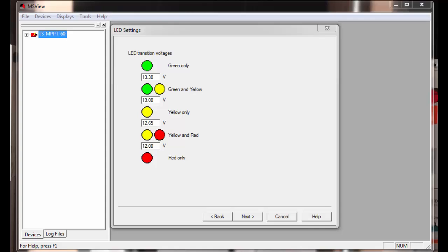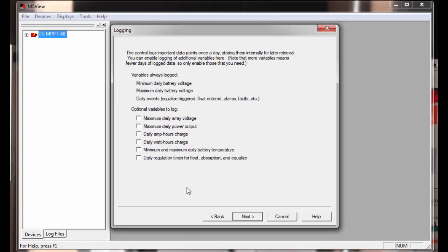And if you're programmed for a different voltage like 36 volts, you would want to adjust these settings accordingly so that it corresponds to the voltages for a 36 volt battery. So 9 volt nominal if you're charging for 48 volts, and then other types of batteries might be a little higher or a little lower, so something to consider possibly, but for lead acid you should be fine with these settings. So going on to the next screen, I just want to mention that up until this point, all the settings can only be enabled with switches 4, 5, and 6 up.